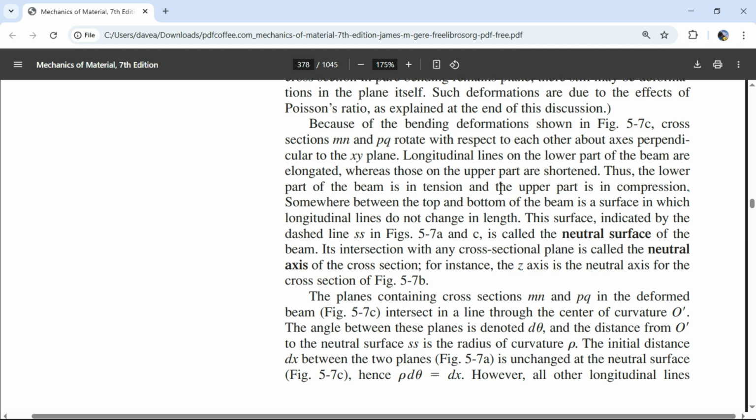Cool. And so that's the heart of material mechanics, and that goes even unsaid. They should just keep explaining that I don't have to pull on steel with a gauge that says, hey, this is how many pounds I'm pulling. Well, what comes first, the chicken or the egg? Like, you have a length of steel, and then you pull 100 pounds on it. And then with electric gauges, just because the distances are so small, you can measure the change in length.